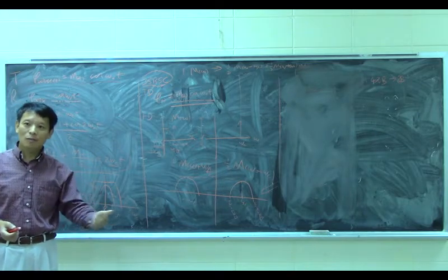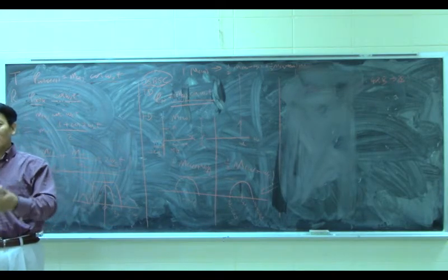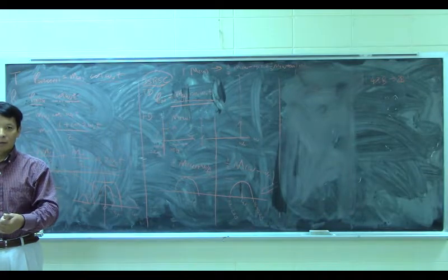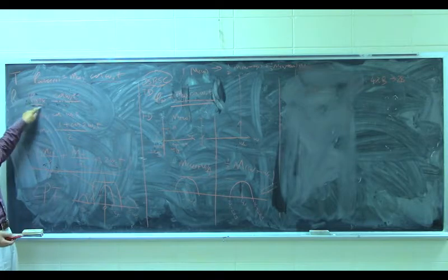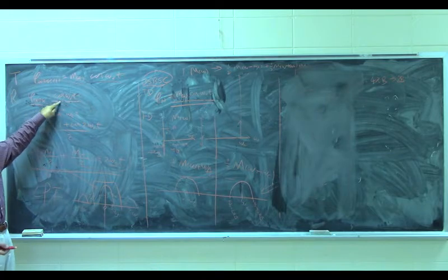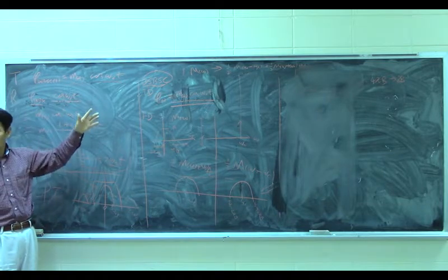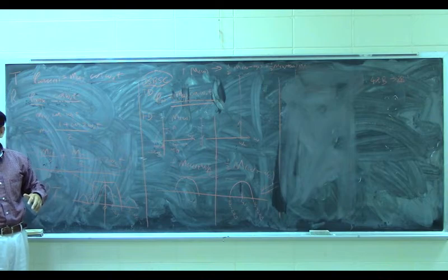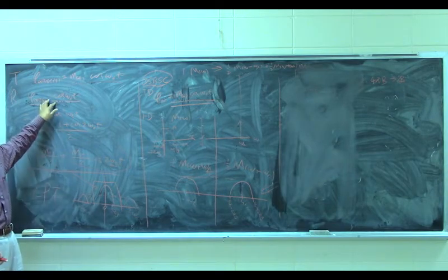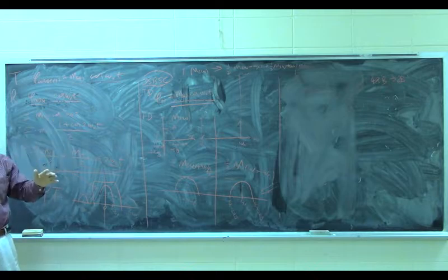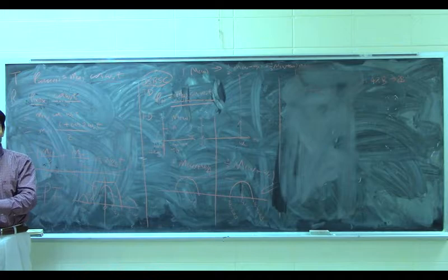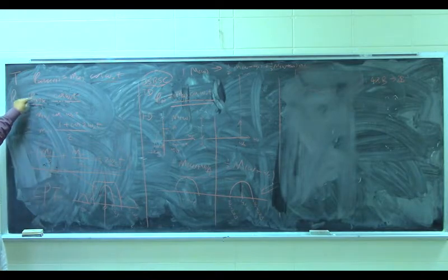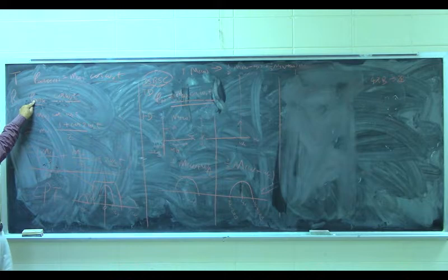You have your baseband signal, multiplied by a carrier, a cosine function. Are we doing this at the receiver also? Yes. You have this signal, although it's not a baseband, it is a signal. Then you multiply by cosine. So that means you are still doing the modulation process in time, so in frequency, we are going to shift your spectrum to a higher frequency, right?